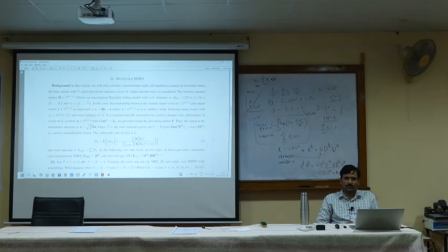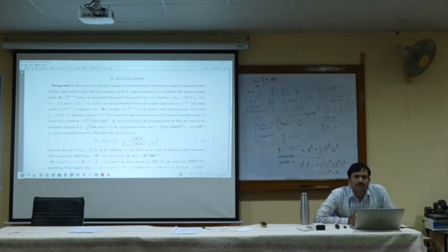We have spoken about scattering. In a wireless environment we have reflection, refraction and diffraction, and also the multipath. That will again have an impact on the uncorrelation. We want a lot of scattering, a lot of reflection, then we will get uncorrelated channels. So not only scattering, reflection also. Everything will help; they add up and help in uncorrelation.